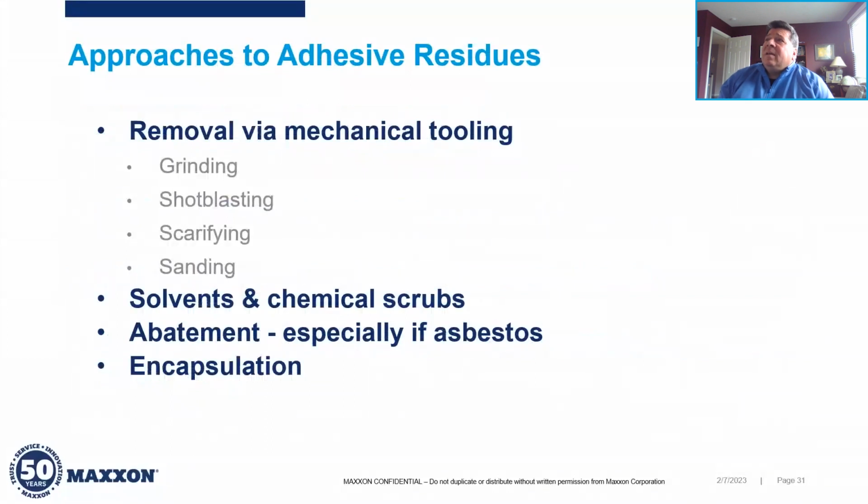So traditionally, when you're dealing with floor spaces that have old adhesive residue, mechanical grinding or removal has been the method of choice. And you're talking about grinding, shot blasting, scarifying, or sanding. These tools require some sort of grinding discs or stones or pads that when they get gunked up with adhesive, they're not good anymore, and they're not cheap.